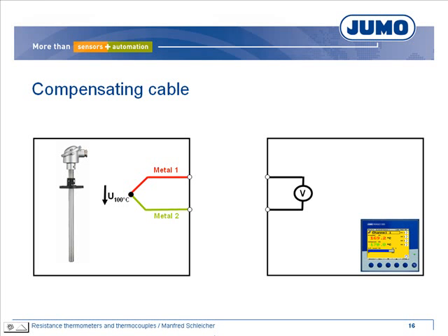So far we assumed that the thermocouple is directly connected to the device. But often connection cables are necessary. For the internal temperature compensation, the second thermoelectric voltage has to occur on the terminals of the field device. From this it follows that a compensation cable has to be used for the connection, which has to have the same thermoelectric characteristic as the metals of the thermocouple. The reference junction results in the field device.